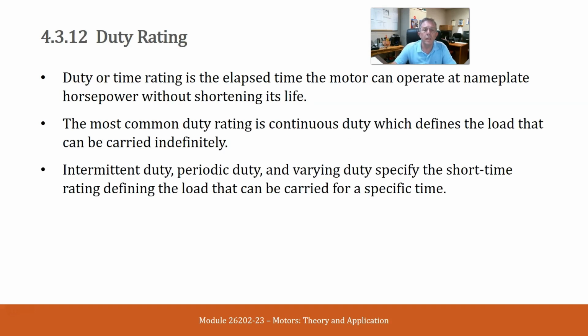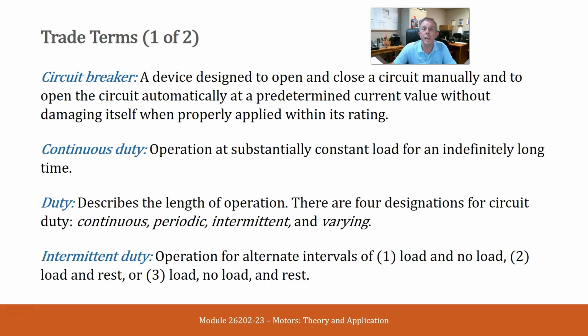Duty rating. Duty or time rating is the elapsed time the motor can operate at nameplate horsepower without shortening its life. The most common duty rating is continuous duty, which defines that the load must be carried indefinitely. Intermittent duty, periodic duty, and varying duty specify the short time rating, defining that the load can be carried for a specific time. And here are some trade terms that you should read over and become familiar with.